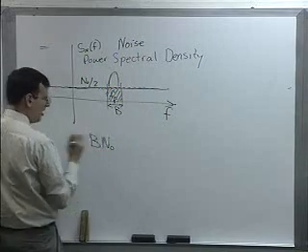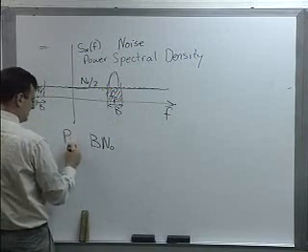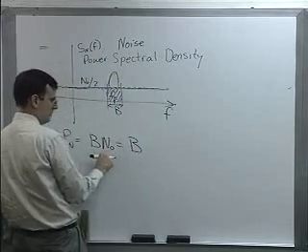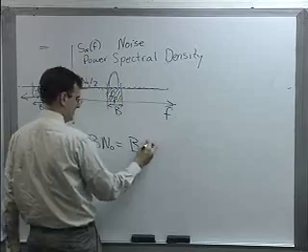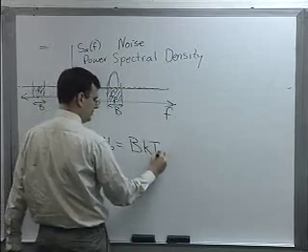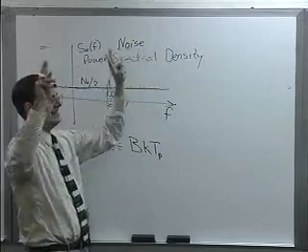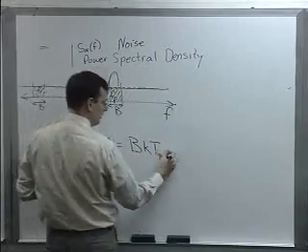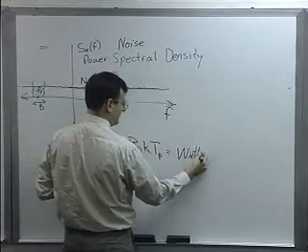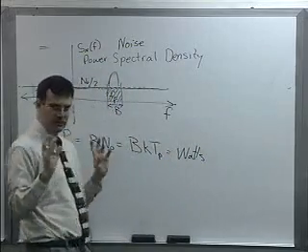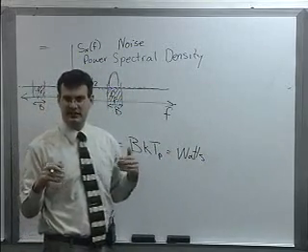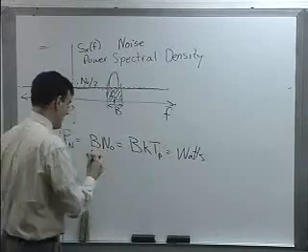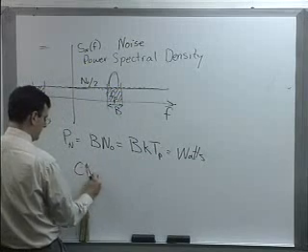And we said that we can also calculate this as B times Boltzmann's constant K times the physical temperature, the average temperature that the antenna sees in its environment. This has units of watts and is probably one of the most important parameters in a system that isn't limited by interference, because this determines your carrier to noise ratio.